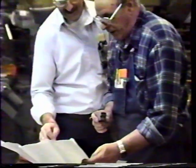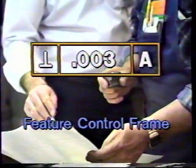GD&T is a technical drawing language whose symbols are recognized and understood by engineering, production, and inspection personnel worldwide. The symbols appear on the drawing in a box called the feature control frame. Only a few symbols are needed to communicate the design requirements for a part feature. The use of these symbols ensures that drawings are interpreted in the same way by everyone.